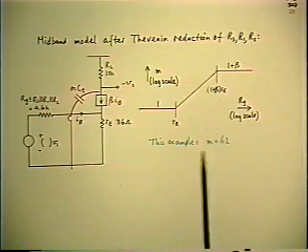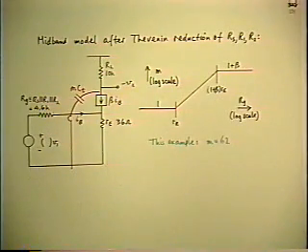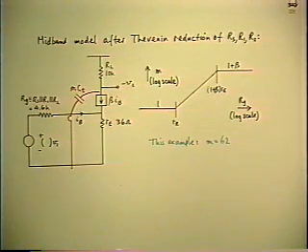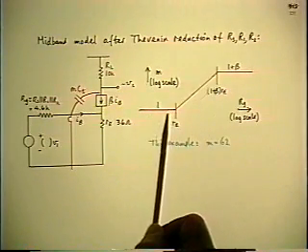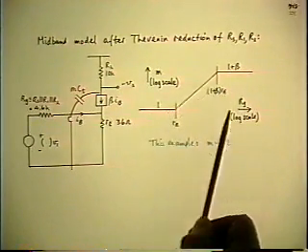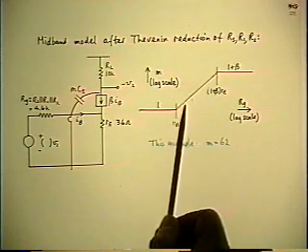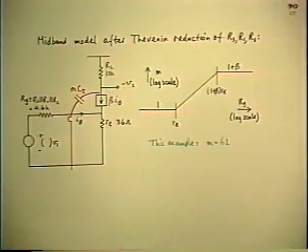What this tells you is, if you consider the Rg as a design parameter that you have some control over, and you want to make a high bandwidth amplifier, then you want to keep the M low, so you want to be near the bottom end of the sketch. So you make the Rg small. You can make it as small as about Re, and there's no further benefit in making it smaller than that.